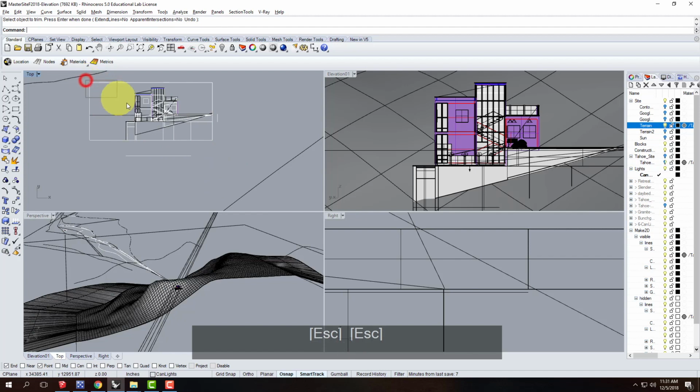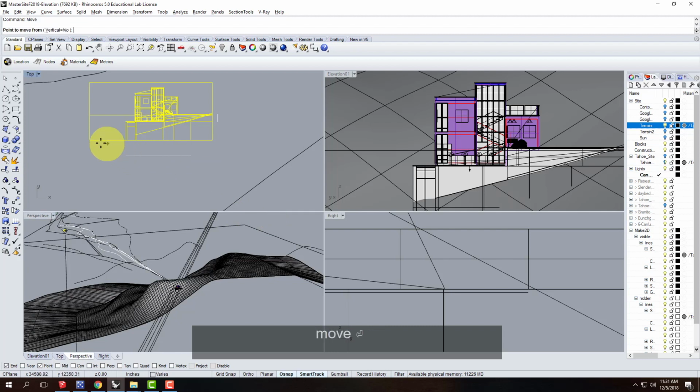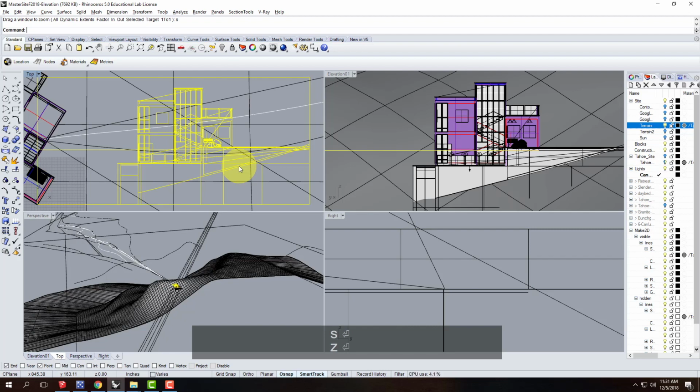And then I will take the stuff that's in the box, that's the part that matters, and I'm going to move it from this corner to 0,0,0. In order for the Illustrator export to work, we have to move it to 0,0,0. Then I will type Z for zoom, followed by S for selected, and there it is. It overlaps my drawing, and it's kind of messy, but this is now ready to do the export.